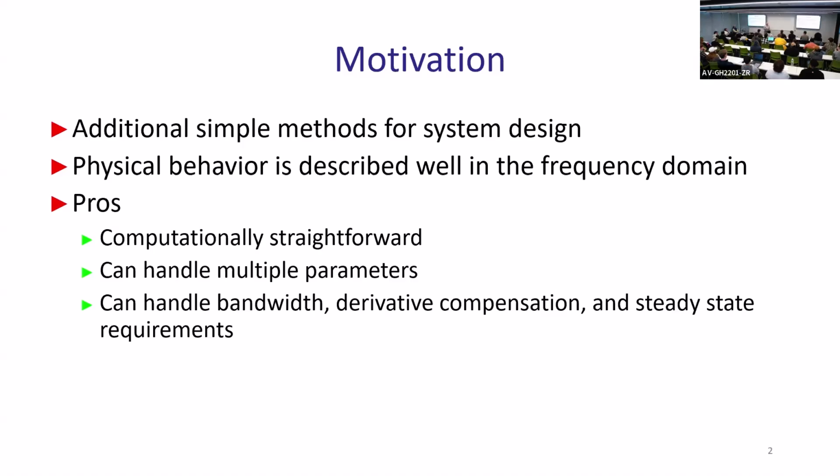It's not necessarily more stable. It actually can be more unstable. Depends. Could more bandwidth mean more noise? This is the disadvantage of higher bandwidth, yes. So the big disadvantage of having wide bandwidth is that you are introducing more noise and disturbances and they all affect your system. And then obviously it's not good for the system.